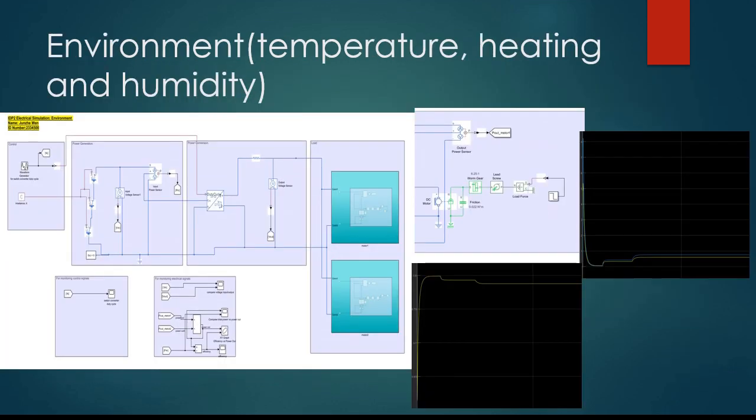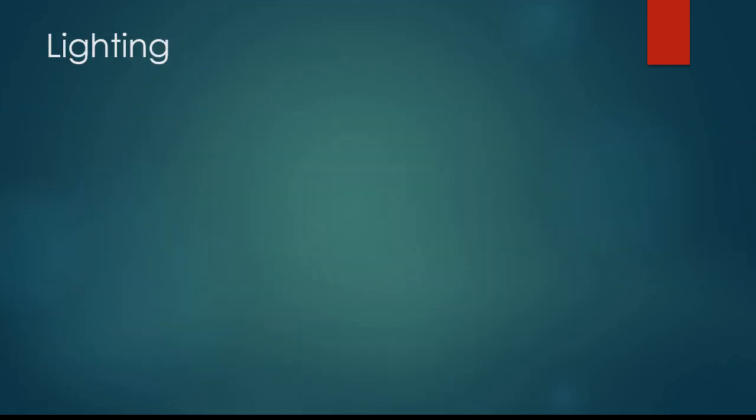Hello, here's the environment simulation part. The left big graph shows a DC voltage source generated by three solar panels so as to make the circuit more realistic. Then an average value DC to DC converter is connected, which is for maximizing the power generation efficiency and maintaining the stability and accuracy of the output voltage.